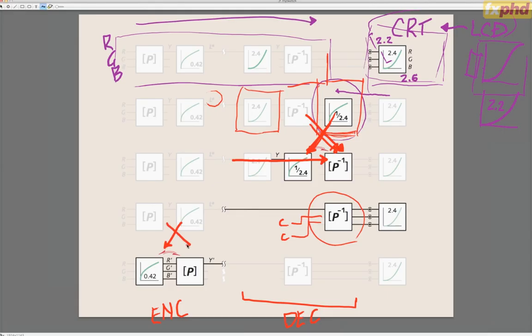So we switch those two operations at the encoder, and what we do in video is first we do gamma, then we do matrix. And the gamma is typically done in the camera of a video system. So your typical HD camera set up in HD mode does gamma correction in the camera itself. Now, the camera may deliver RGB out, but with primes on them, or the camera may also deliver YCbCr, but that's a different story that we're headed towards. But no matter which, the gamma comes first.